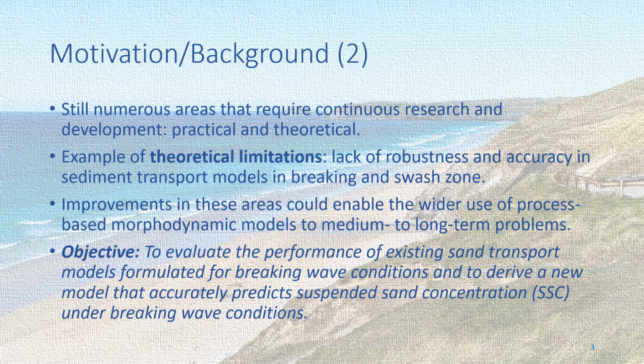Improvement in accuracy and applicability of such sediment transport models could lead to improved performance in morphodynamic models by incorporating the improved transport models into morphodynamic modeling suites such as Delft3D, MIKE21 and Telemac. This could also enable the wider implementation of process-based morphodynamic models to medium to long-term problems.